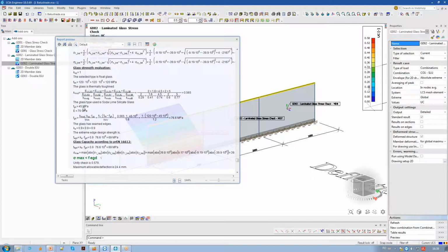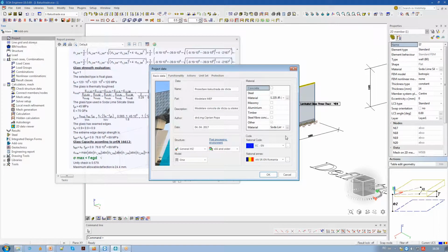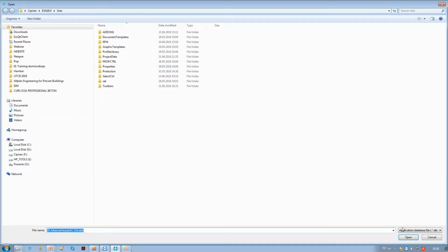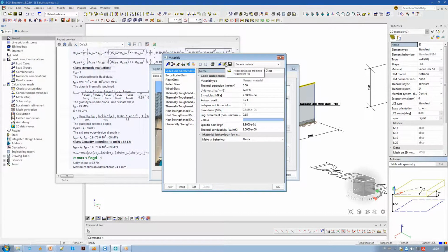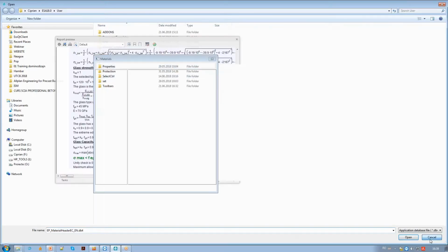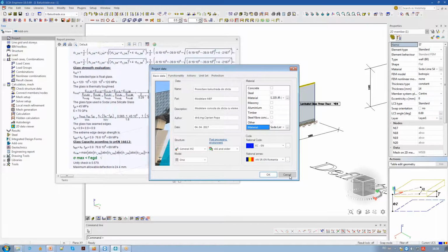And for that, you can import the glass. So I already shared with you through email. With material, this is the database of the glass. I shared it with you. And if you want to add it to your new project, although I'll include it in the shared example, you can read it from here. So I promise I'll show you. This is how we read it. So when we define the new project, you just select other material and read it from this file from the database. In future version, it will be automatically included in SIA, but for now, this is the way it will work.